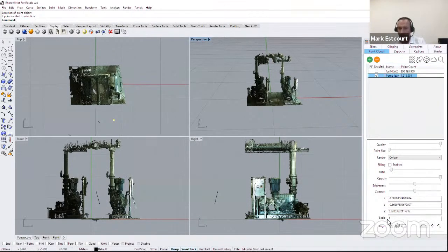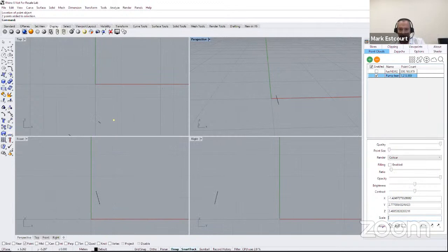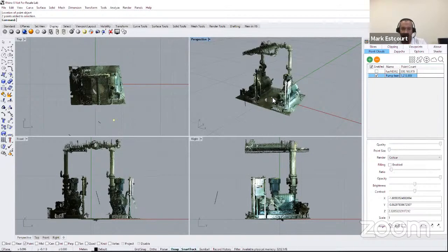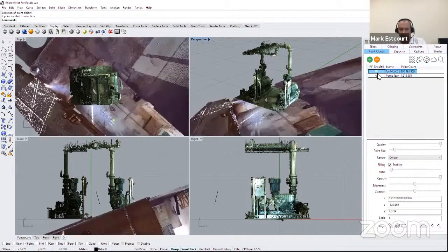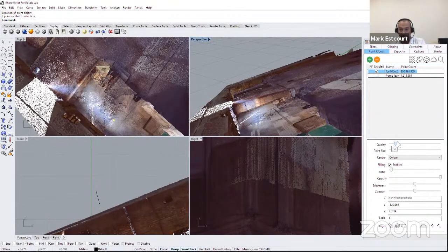Okay, right, so coming back down to the bottom of the point cloud functions, for each of the point clouds you've got a scale option. Now this could be if you've captured the data in meters and you've processed it in meters, but you're working in feet, you can go there and change the scaling for the point cloud itself. Okay, so that's quite useful. Some scanners also do scale the data that you've captured, and it's also easy to come in here and modify that scale in real time as you're using the data.